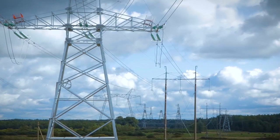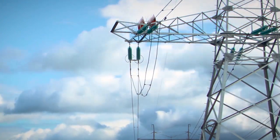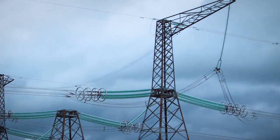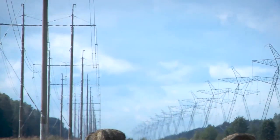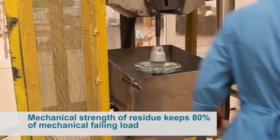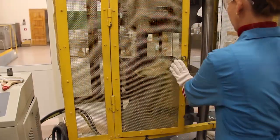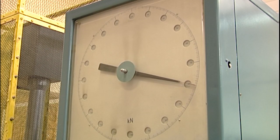An insulating part can be destructed when large external effects are imposed upon insulating part, heavy shock and other mechanical effects, or resulted from overstress, lightning direct hit, switching over voltage, etc. Even if insulating toughened glass part is destructed, mechanical strength of residue keeps 80% of mechanical failing load that eliminates wire and insulator string drop and thus allow operating ETL trouble-free before replacement of destructed insulators.